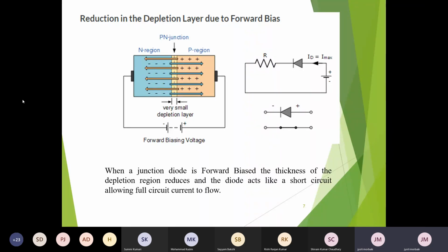In this way, as there is a flow of electrons and holes inside the respective regions, we can observe current through the PN junction, of course when the external voltage crosses the barrier potential. Now, whatever voltage we apply externally is called the forward voltage, and the current that we observe is called the forward current. So forward current and forward voltage are related to forward bias.